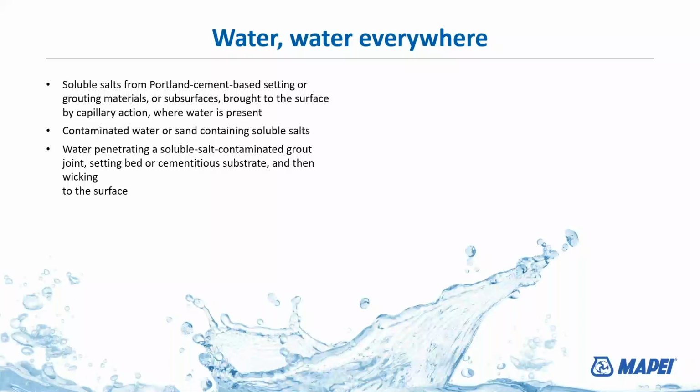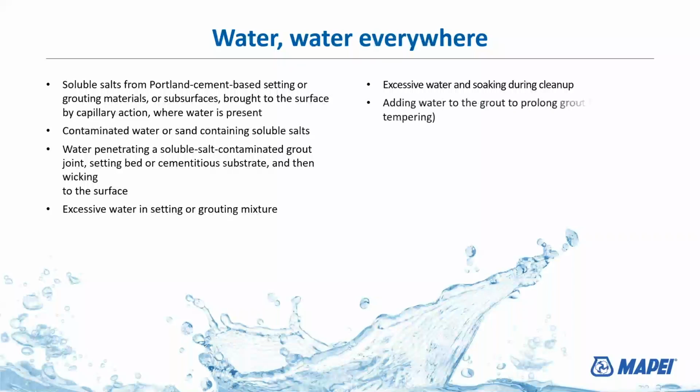More water than necessary in a setting or grout mixture, excessive water or soaking during the cleanup, adding just way too much water. All these things contribute to it. Again, adding water to the grout to prolong the life or retempering the grout with water as you're mixing it. None of these are recommended. You don't ever add water to grout. You might get away with it on thin set or mud beds and things like that, but to do it on grout is definitely going to cause an efflorescence issue.